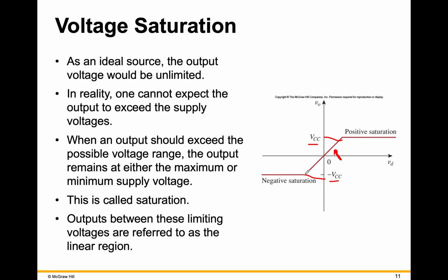If you exceed that range, so here's your V sub D. That's your V plus minus V minus. So that's the difference between your positive and negative, or your inverting and your non-inverting terminals. So if you exceed this on your input, you'll get saturation, and your output will not be linearly proportional to your input. That can be a huge problem. It can cause something called clipping. So suppose you take an AC signal and you put it into your op-amp. If you exceed the